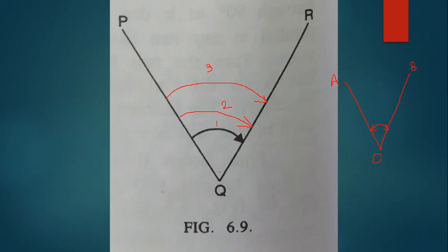So what we are going to do, we can transit the telescope and rotate. By transiting, you're actually changing its face from left to right. Then rotate, release both clamps and rotate in the opposite direction, so that the 0 of vernier A exactly matches with the 0 of the main scale.